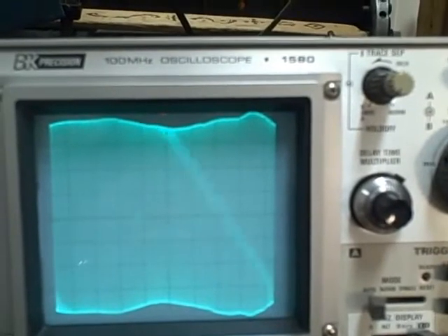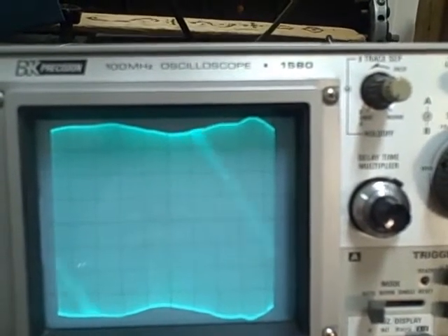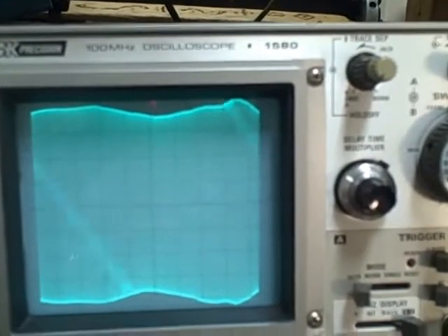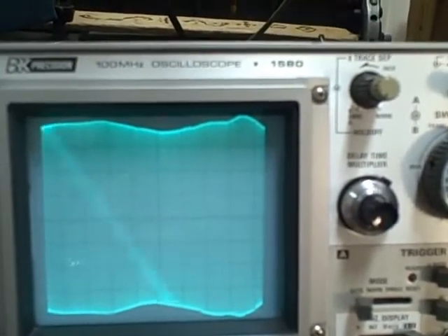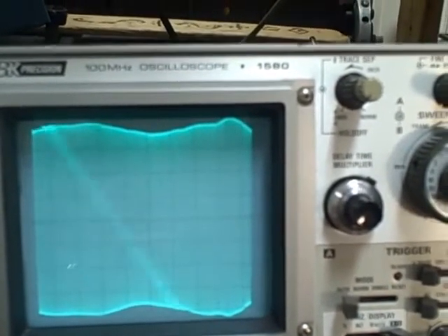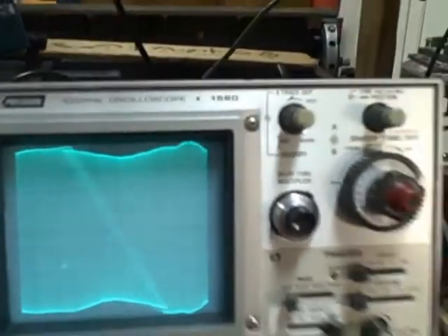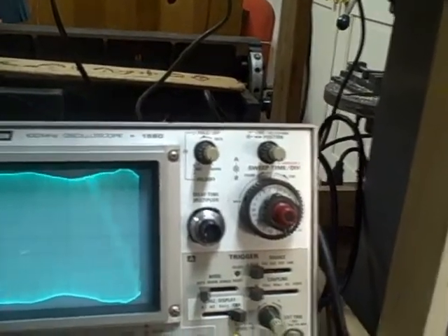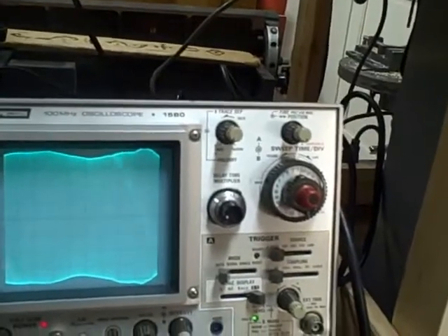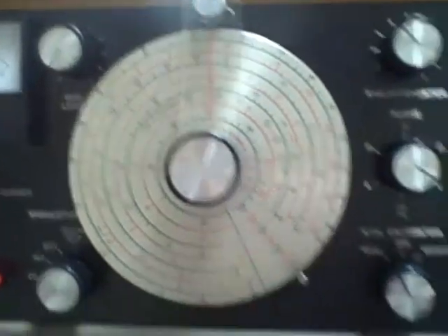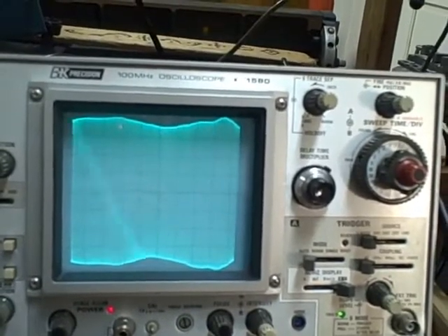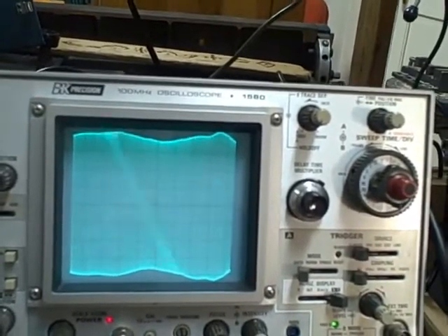So we are not faithfully providing a flat signal amplitude into the scope. So if I'm going to try and read my 30 megahertz scope bandwidth with this, I'd have to bear in mind that my generator is also not capable of producing that signal faithfully. So what am I going to do? Well, we know that we are flat 0 to 10 megacycles, so the generator helped us there. But I am going to put a 30 megacycle RF signal from this RF generator onto the scope, and I'm going to adjust it for 4 divisions on the 20 millivolt scale here.